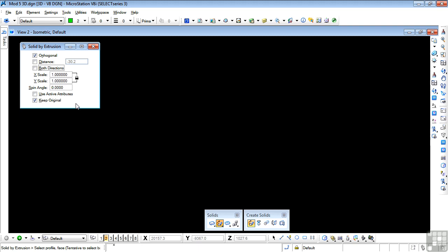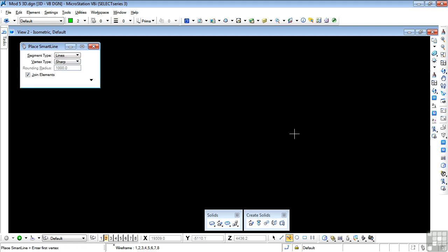You're going to need to switch between a wireframe view and a shaded view, and I assume that you've already set 2 function keys for this purpose. Let's start by looking at a simple angle. So make the settings that I have in here, except that I don't want to keep the original at this point. So only orthogonal is on. And we're going to draw with SmartLine. So start, I'm in the top compass orientation, and no dimensions here for the moment. So I'm going to draw myself an L shape. Again, doesn't matter what dimensions I use. Hit enter and find that point and snap back.